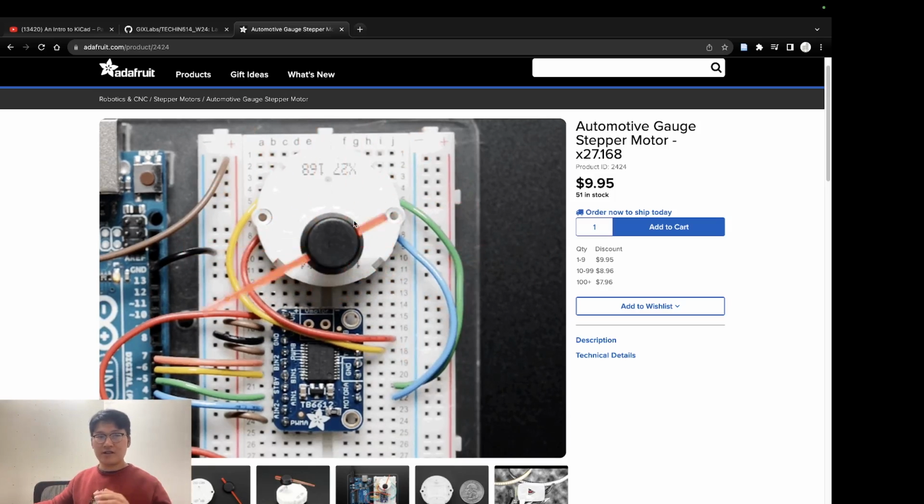So they have some advantages, but for now, my point is that it is definitely possible to power and control this stepper motor directly from your analog output pins on your MCU without using any drivers. And if you do have specific usages, say you want some complicated computations on your MCU and you want the stepper motor's control to be non-blocking, we can definitely use a driver.